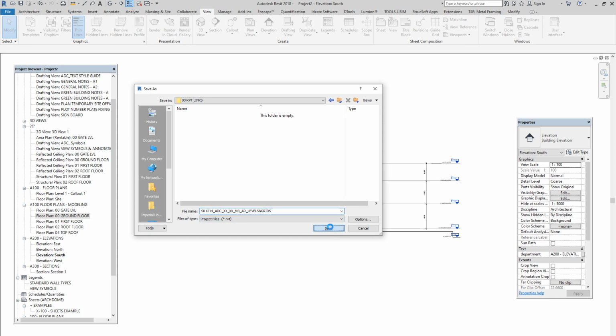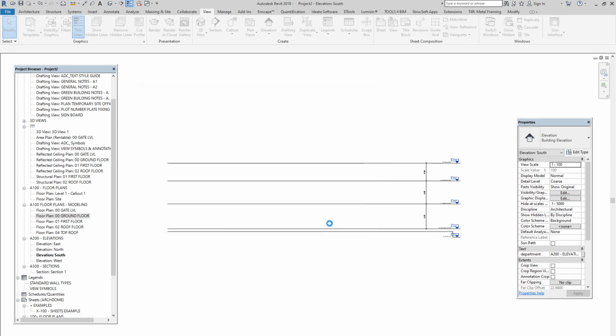Now we are saving as a normal model. Later on we have to save it also as a central model, and we will explain why we have to keep it as a central model, not as a normal model, to ease the way of linking into the project. By one easy step we can create it as a central model, just now it's a standalone file.